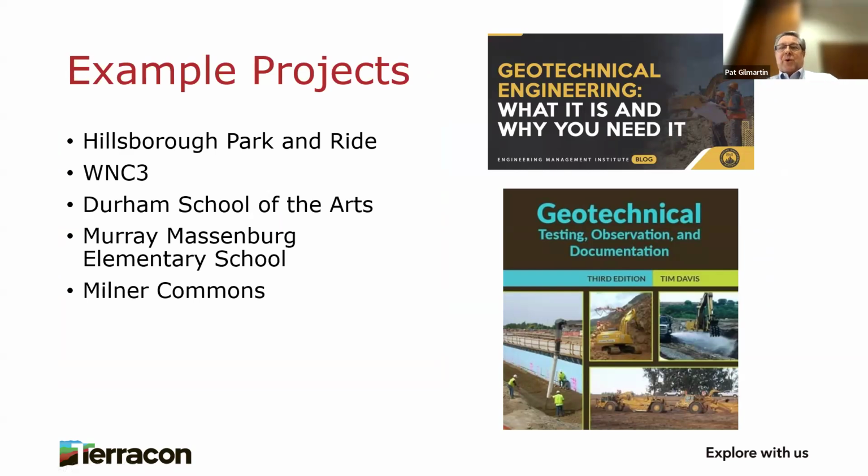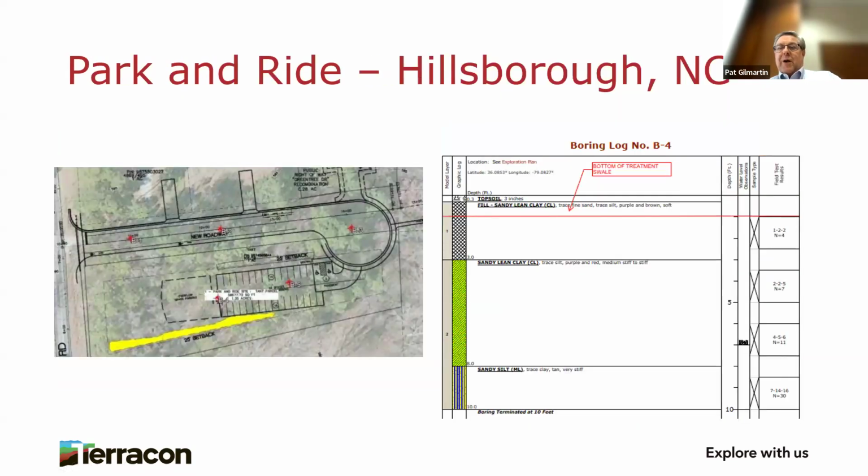I'll discuss some real world project examples, which are intended to demonstrate some of these issues that I've been discussing today. The Hillsborough Park and Ride project consists of a new public roadway with bus traffic and a personal vehicle parking lot. Terracon initially drilled borings for the proposed grading and pavements, which encountered some clay fill over Piedmont residual clays and silts. Groundwater was not encountered within 10 feet of the ground surface. The site civil engineer then let us know that they were considering using a stormwater treatment swale on the south side of the parking lot, which was going to be excavated only about a foot below the existing grade.